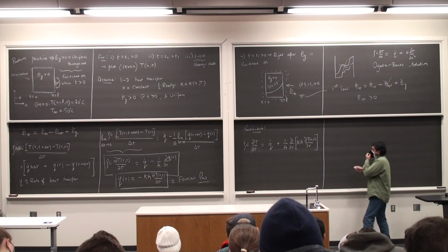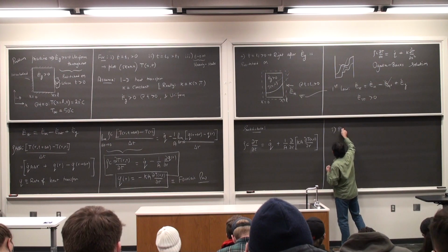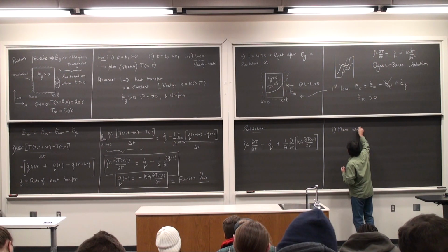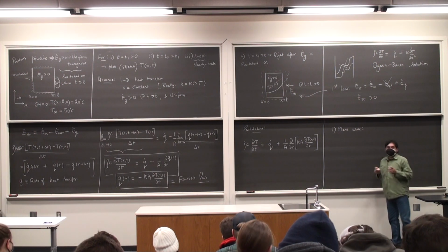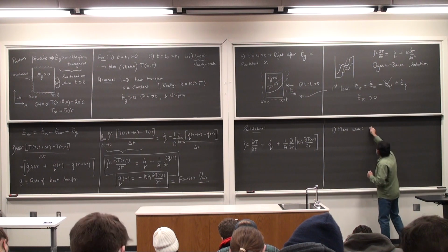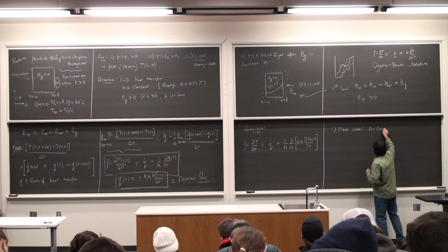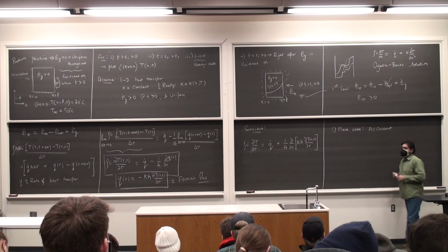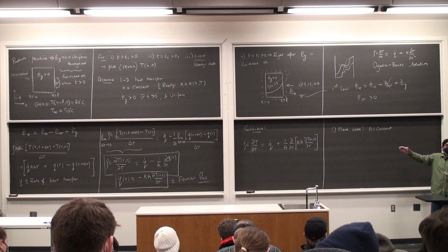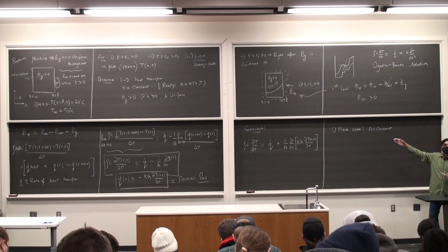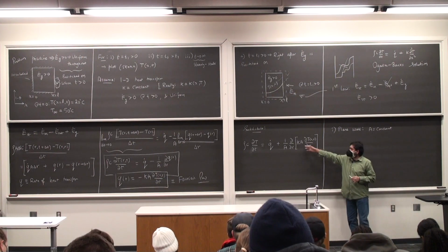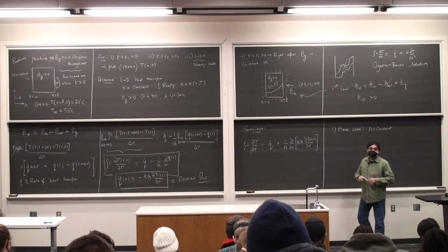Look at this. Plane wall, area is a constant. And so you can get rid of the area terms, 1 by A and the A which is within this derivative here. So I can get rid of these two terms in the plane wall situation.